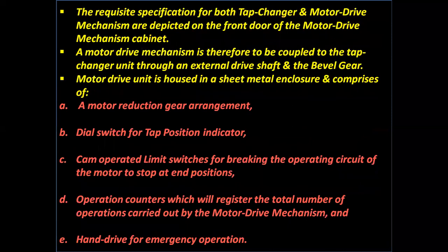The requisite specifications of both the tap changer and the motor drive mechanism are depicted on the front door of the motor drive mechanism cabinet. A motor drive mechanism is coupled to the tap changer unit through an external drive shaft and the bevel gear.